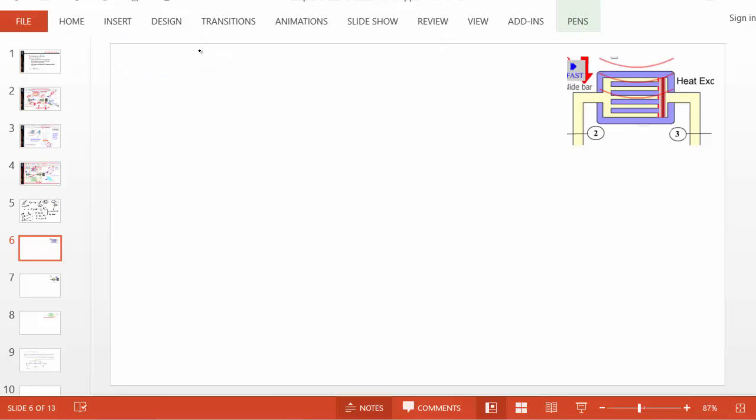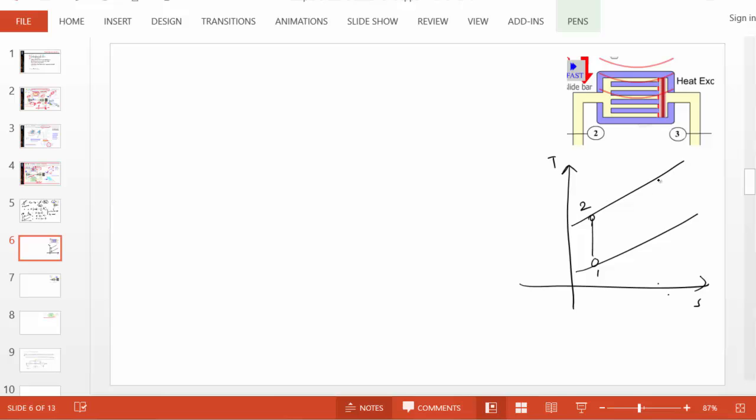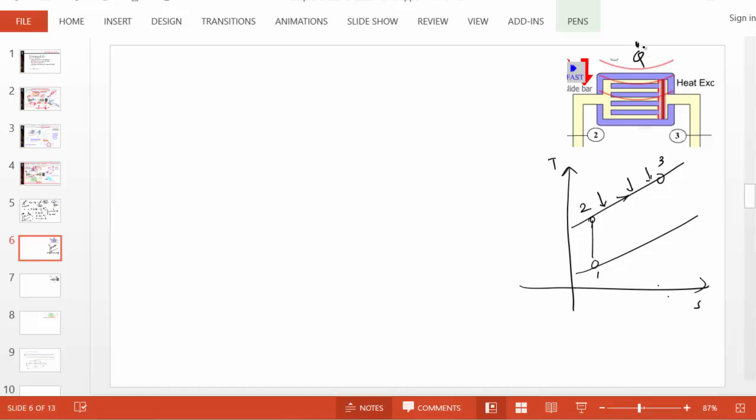So we are modeling here a constant pressure heat addition. Let's do it on a TS diagram first, how it will look. So we have already analyzed the compressor, and from 2 to 3 is our constant pressure heat addition, if you recall. So if we call the heat addition Q dot in, we want to find an expression for Q dot in. Again, starting from the energy equation for an open steady device, m dot, instead of J, let me just directly use H. Instead of J, we are using H because kinetic and potential energy are mostly negligible.